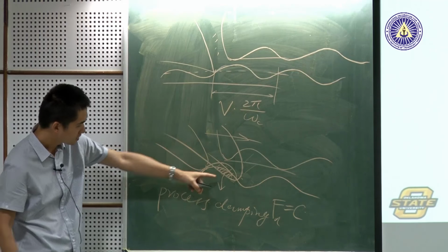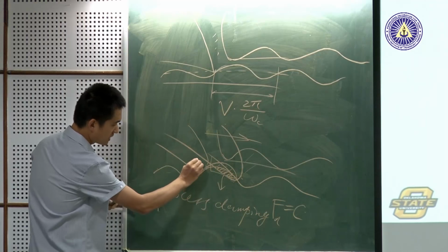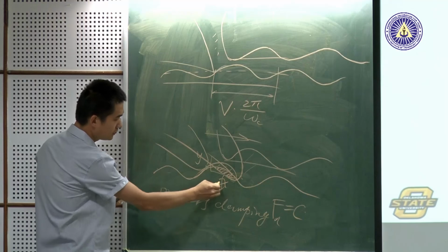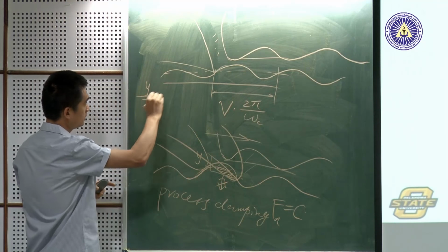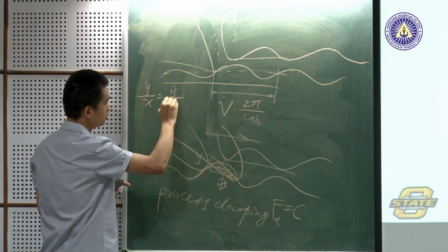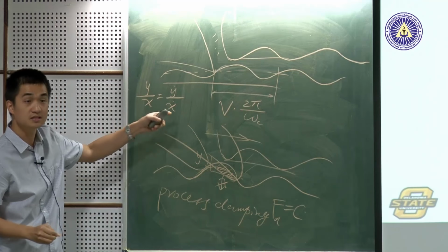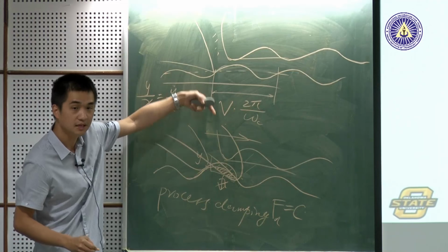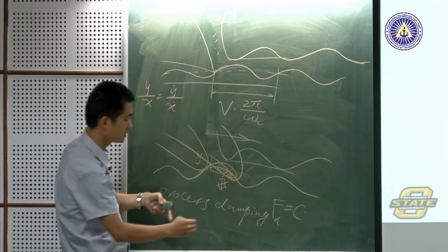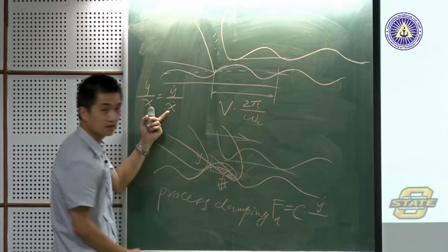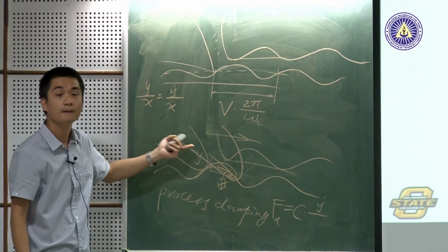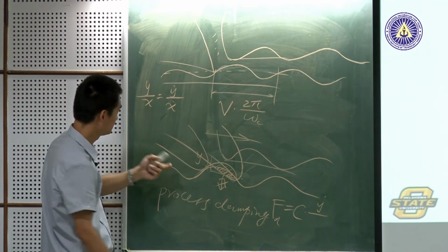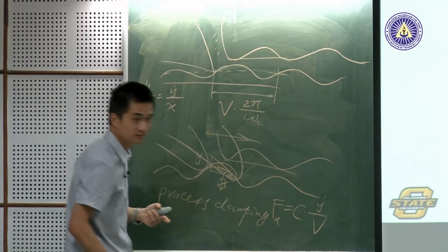So how do we calibrate the slope? Slope is basically the displacement y over x, right? That's how we define slope. But since we don't know the y and x, why don't we just put y dot over x dot? It should still be the same if you take the derivative. Now, what's the y dot? Y dot is the vertical velocity in the feed direction of the workpiece. And what's x dot here? Anyone can tell me? Cutting speed, right? X dot is the cutting speed.